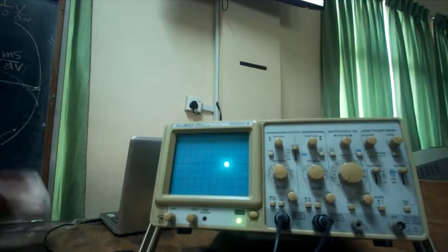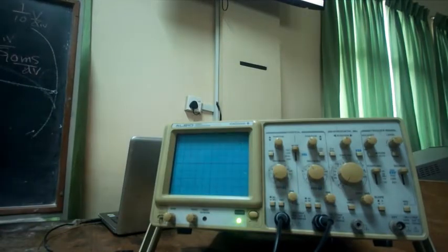So there is this time per division knob that you have on this. It's basically a variable resistor or something like that. It changes the slope, and that voltage is given there. This is a sawtooth generator, a triangular wave generator. It sends a voltage there. So what you see here is something like that. Correct? Does everybody understand this concept?